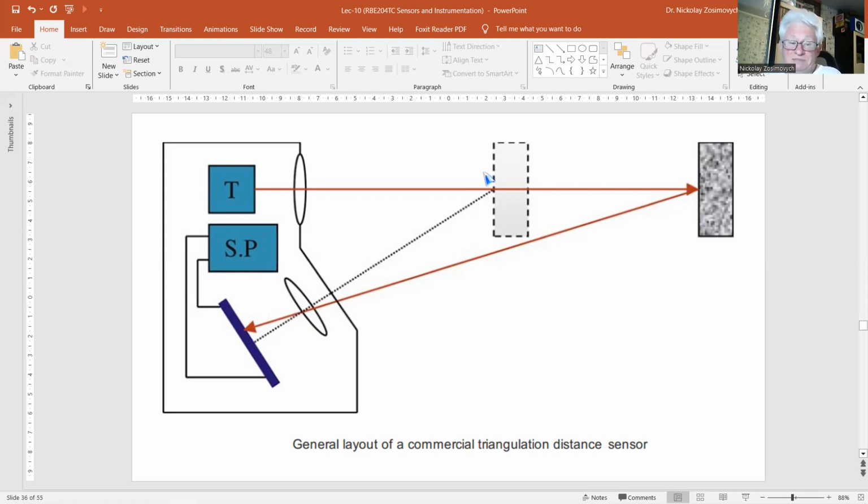An example of a displacement sensor using interferometry in combination with the feedback principle. The system uses the speckle effect of a laser beam falling on a non-specular surface. Speckles are randomly distributed light and dark areas on the surface. This speckle pattern changes with the distance from the laser to the surface. The feedback system uses this dependency.